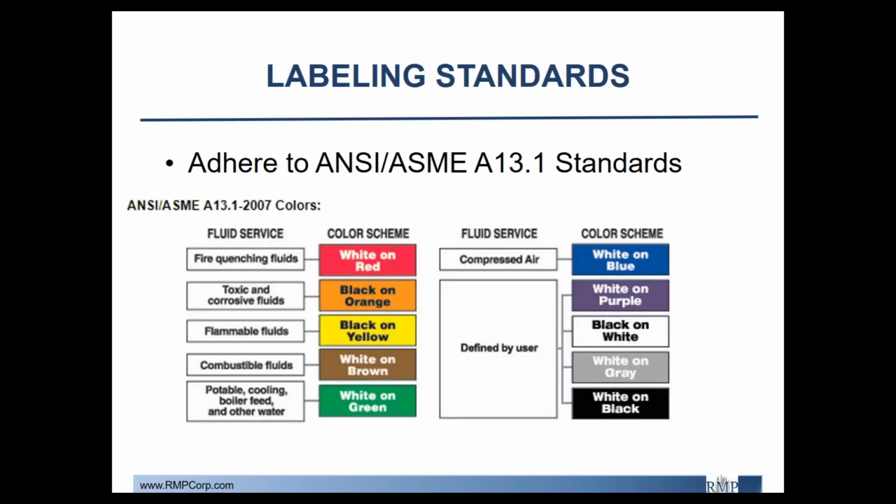All right, so I'm going to wrap this up with talking about how labeling comes into play. The reason why accurate P&IDs go hand in hand with labeling is because, as I said before, there's often a delay in updating one over the other. So when you're labeling your valves, you're labeling your pipes, and you're making changes in your P&IDs at the same time, that's where you run into the issue of doing double work. So we just wanted to go over some basic labeling policies and techniques that you should follow.